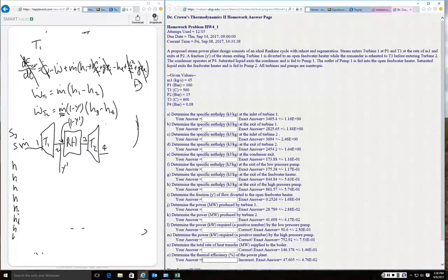And then since we have the diagram here, let's jump next to the reheat. For the reheat, we're trying to find the heat transfer in using our first law equation up above. We're saying it's steady state. There's no work for the reheat, and we're left with 0 equals Q dot plus m dot, and assuming there's no change in kinetic or potential, we have h inlet, which is h2, minus h exit, which is h3.